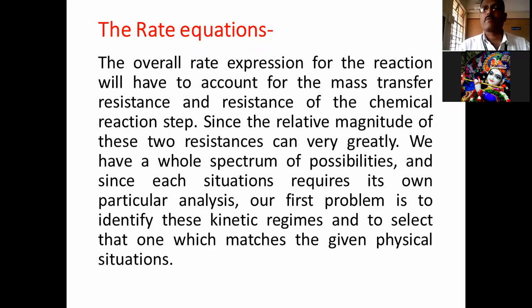Okay, in the interface mass transfer, when the two fluids come in contact, a gas film and a liquid film are formed. These film interfaces are formed, then solute is transferred from the gas film to the liquid film. Means there will be a mass transfer resistance, the gas film resistance and the liquid film resistance. Another, second resistance will be the kinetic, the reaction rate resistance. Then reaction resistance will occur, and where it actually occurs, this regime needs to be identified.